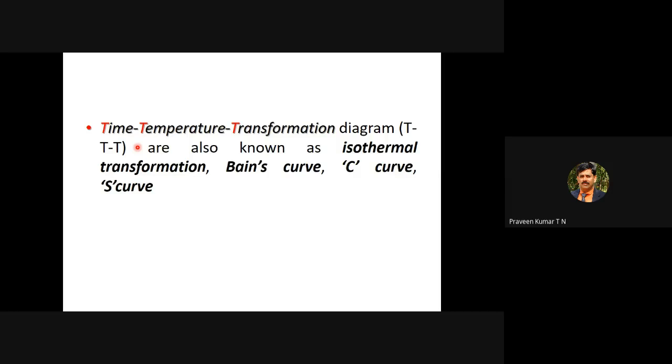We have austenite, we have the eutectoid reaction. Now we are not worried about the eutectic reaction in the iron carbon diagram. When you come to heat treatment, most of the time you are concentrating only on the eutectoid reaction. Eutectoid composition is 0.8, and the eutectoid reaction takes place at 727 degrees Celsius. In the eutectoid reaction, gamma or austenite is transformed to pearlite, which is nothing but alpha plus Fe3C.